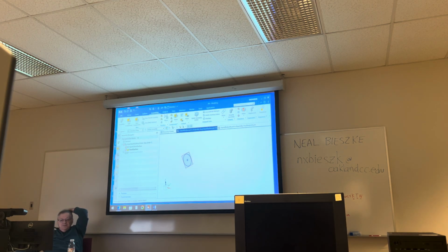Then it says, in the part navigator, we got this guy called, look at it here, part navigator, oh, it's under form, I'm sorry. It says, locate the body side main slab, it's that guy. I had it hidden in mine for some reason, but there it is, all right? We wanna make it the current feature. Because what we're gonna do is we're gonna take that, and there's a tool in NX that lets you make the original root slab from this. This is trimmed.